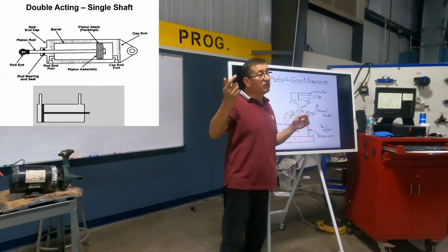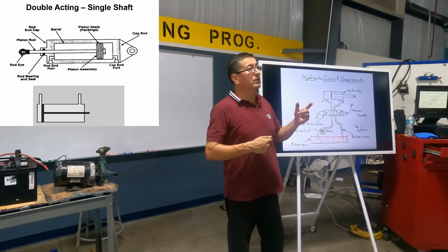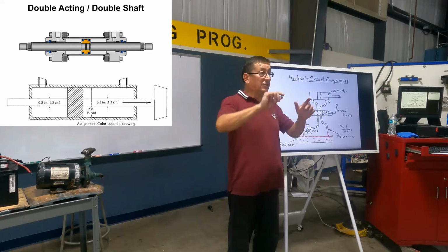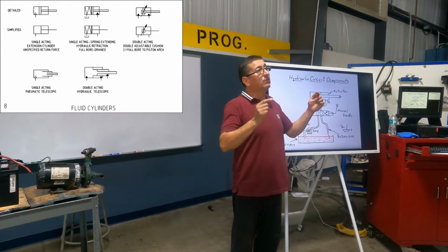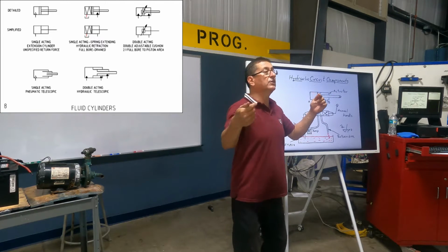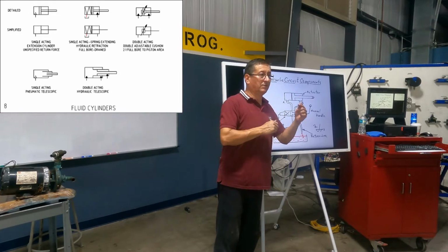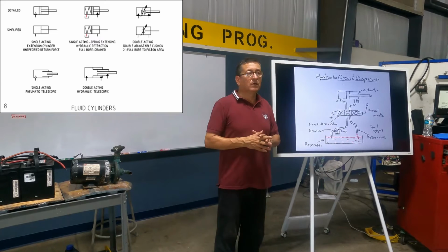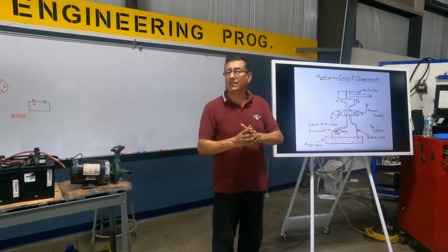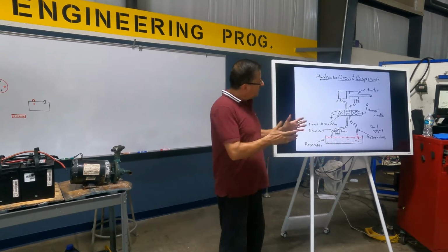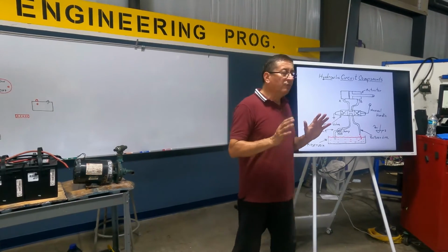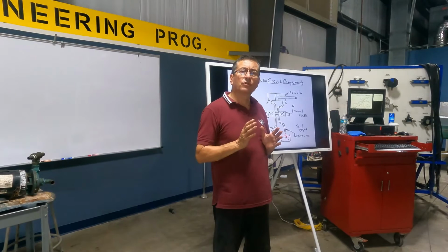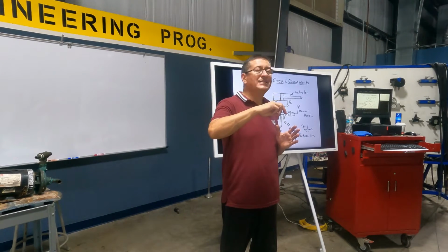Single port, single shaft; single port, double shaft; double port, double shaft; telescopic; or single port, single shaft with a spring return, like the twin taps. We are going to check later. Different applications depending on where it is located and what the function is. This is the typical hydraulic unit. The majority of those hydraulic units in your boat work with reversible motors, AC and DC.